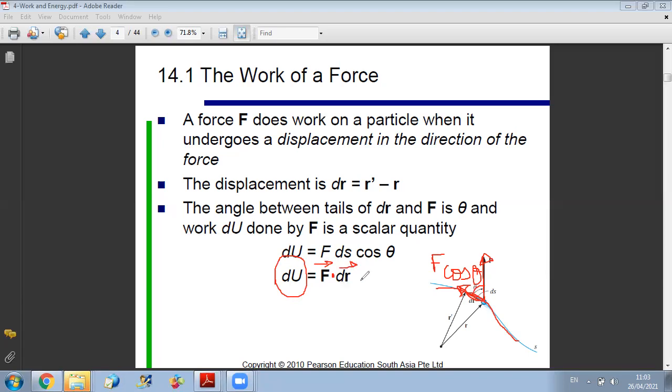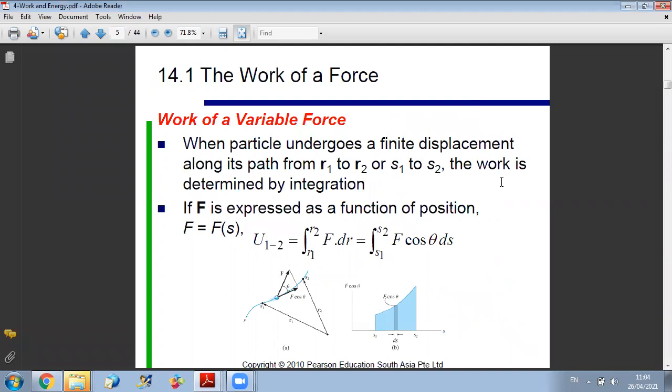Okay, so here, in case the force is perpendicular to the displacement vector dr, this means no work. And in case it's collinear, then the work will be F times dr. In case F is directed along the displacement, so if they have the same sense, it's a positive work. If they have opposite sense, it's a negative work. Please stop me in case there is something not clear.